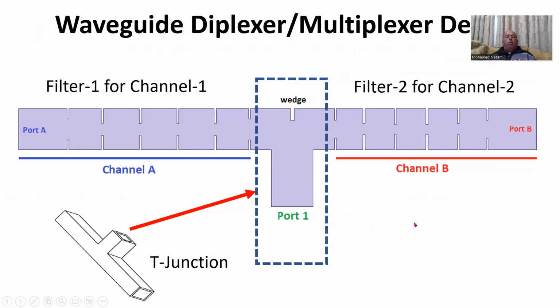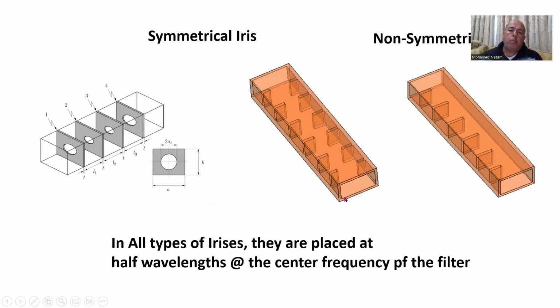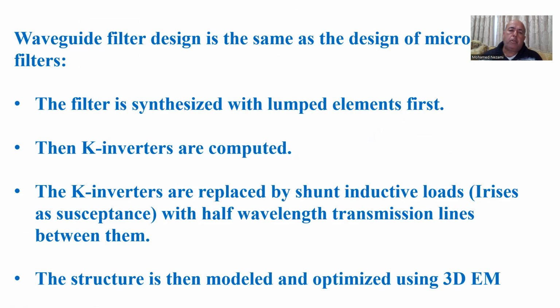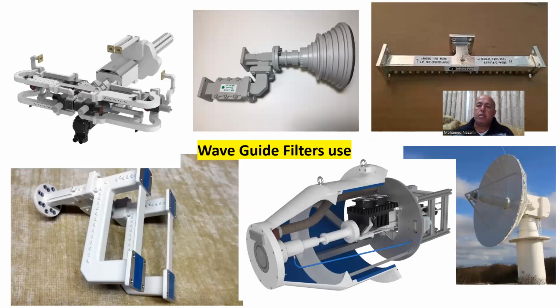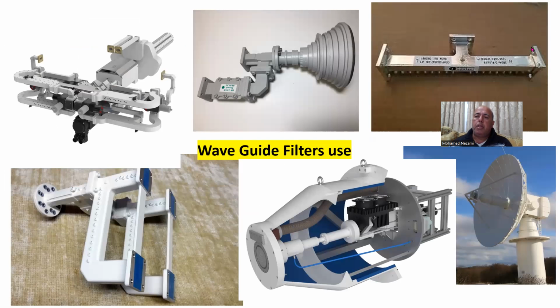Now, although we talk about filters in waveguides, a lot of times the reason we design a filter is because we're designing a diplexer, for instance, like this here. In this diplexer you could have a receiver in here, a receiver in here, and then you need to combine them with filtering in between. Or you could have a transmit and receive also.